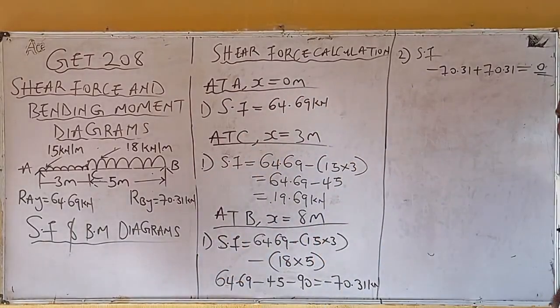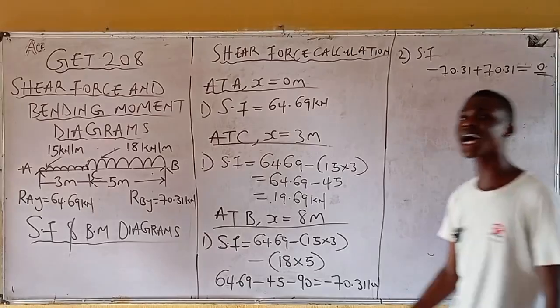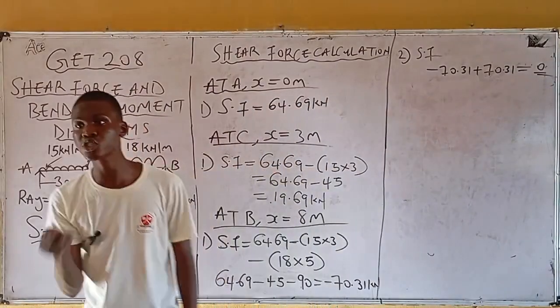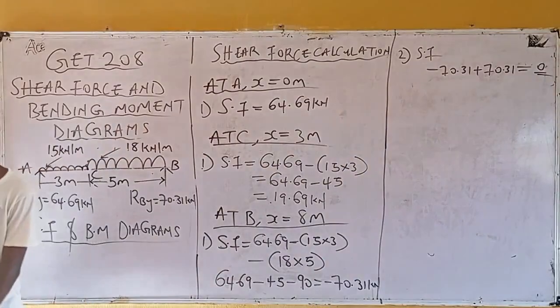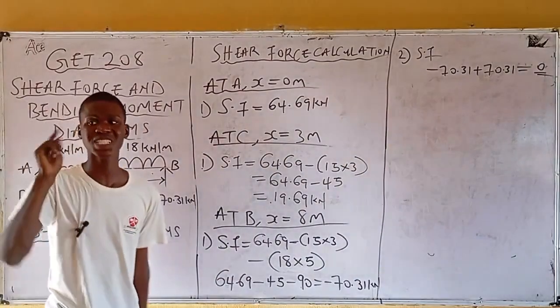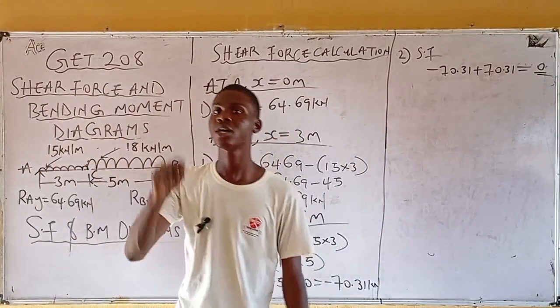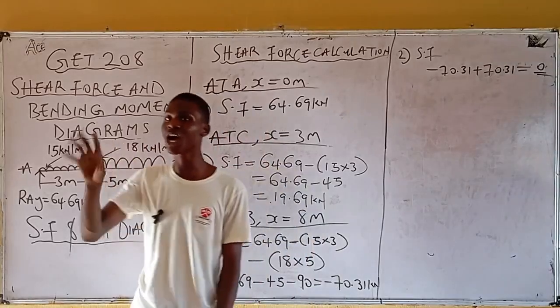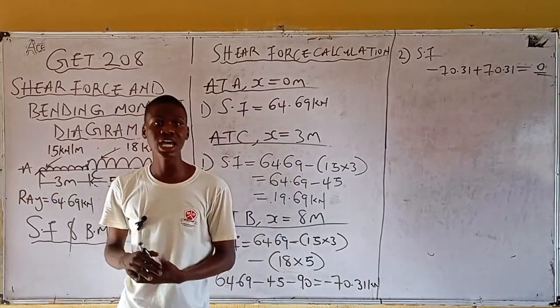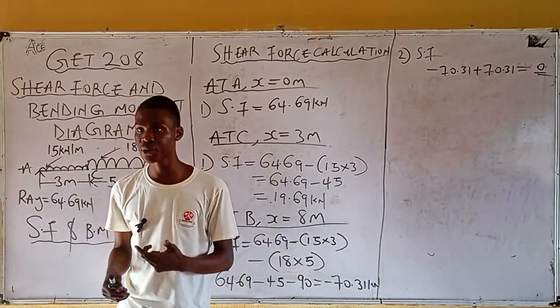Your choice. So now from here, you can see that you are solving a particular question for shear force and bending moment diagram. It's something that you can see if you are correct or not, just because at the end it will end with 0. It will end with 0.